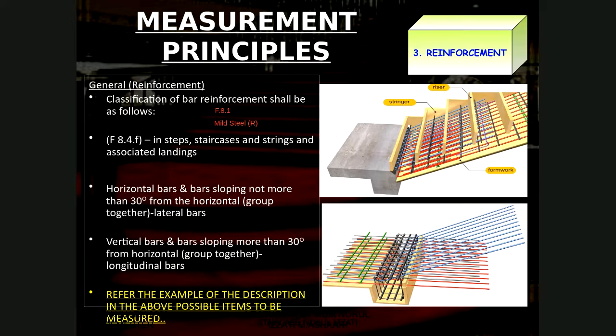High tensile is referring to Y, or sometimes you can see T. T is normally deformed high tensile, which normally has rougher surfaces compared to Y. Okay, Y is more expensive, and of course the abrasion between the concrete is better. These two are clearly stated in F.8.1.